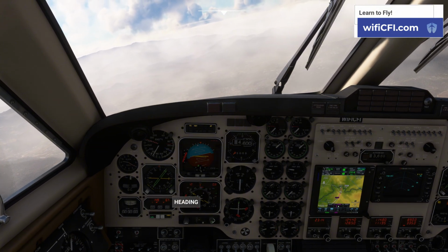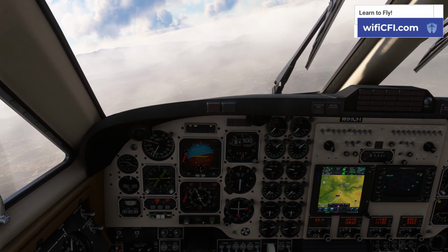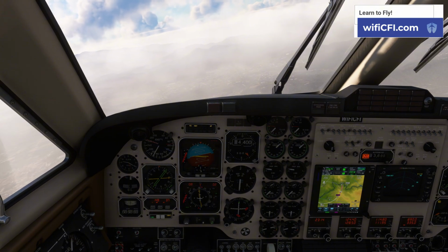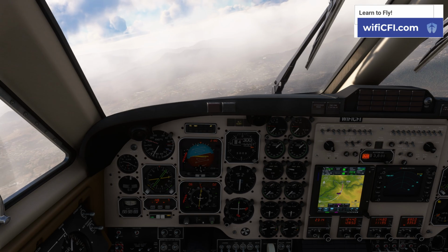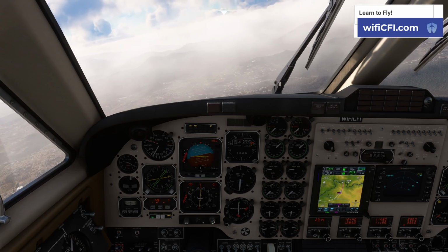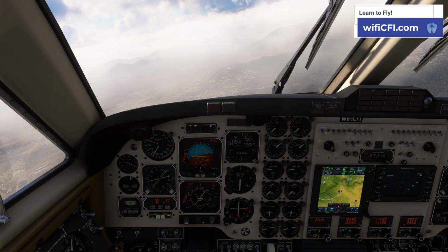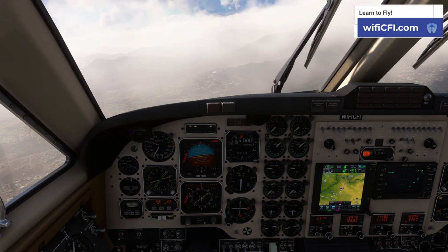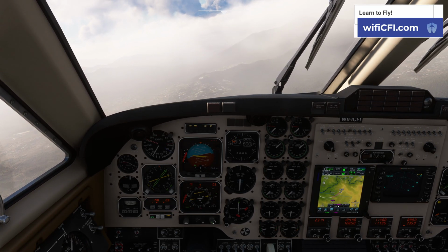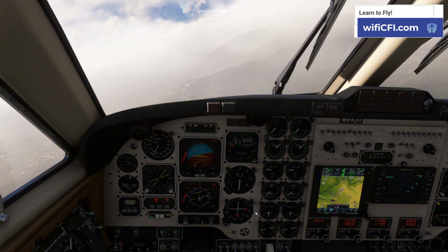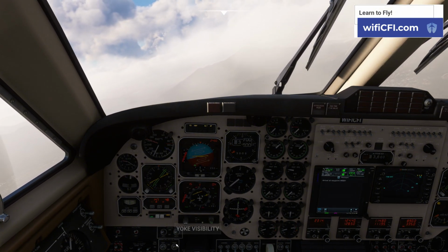And then keep an eye on it. Approach course 200, or sorry, desired track 200. If our approach course was, I might just put it on that 281 because we're going to keep this turn coming around. See how it keeps turning. 281 here. Maybe. Good.